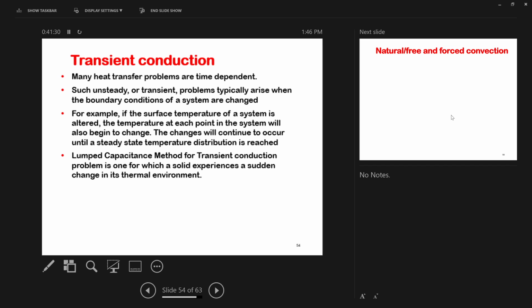So the temperature inside is T, the same as the temperature on the surface. Does it make sense? You are essentially removing the temperature gradient inside the solid ball, which means that you won't have the conduction anymore, right? It will be a one-dimensional polar heat transfer, but it's a one-dimensional heat transfer nonetheless, right? So if you can apply the lump capacitance method, you only have to deal with a very simple convection. The only catch is you have to be able to calculate a heat transfer coefficient, and that is what we are going to focus on.